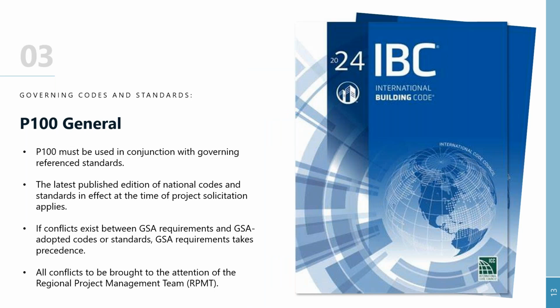So P100 is intended to be used with national codes and standards, and more, I'd say, clarity on the latest published edition of those standards, not necessarily the local jurisdiction and what code version they've adopted. This is taking the perspective that GSA knows it takes a while until the project is completed construction, and typically by then that latest standard is now in place. So thinking ahead on the life of their buildings, they want to make sure that they're designing in accordance with the latest published versions. Again, no difference: if there is a conflict between the P100 and the codes and standards, bring it to the attention of the regional project management team.